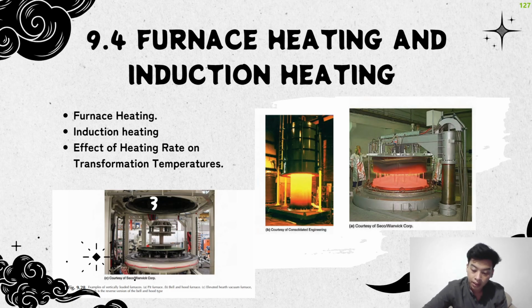Furnace heating. Heat treating furnaces can be generally classified as either batch or continuous furnaces. Batch type furnaces are where loads are placed in the furnace. The furnace and its loads are brought up to temperature together, and depending on the process, the furnace may or may not be cooled before it is opened and the load removed. Continuous type furnaces operate in an uninterrupted cycle as workpieces pass over a stationary hearth or the hearth itself moves.